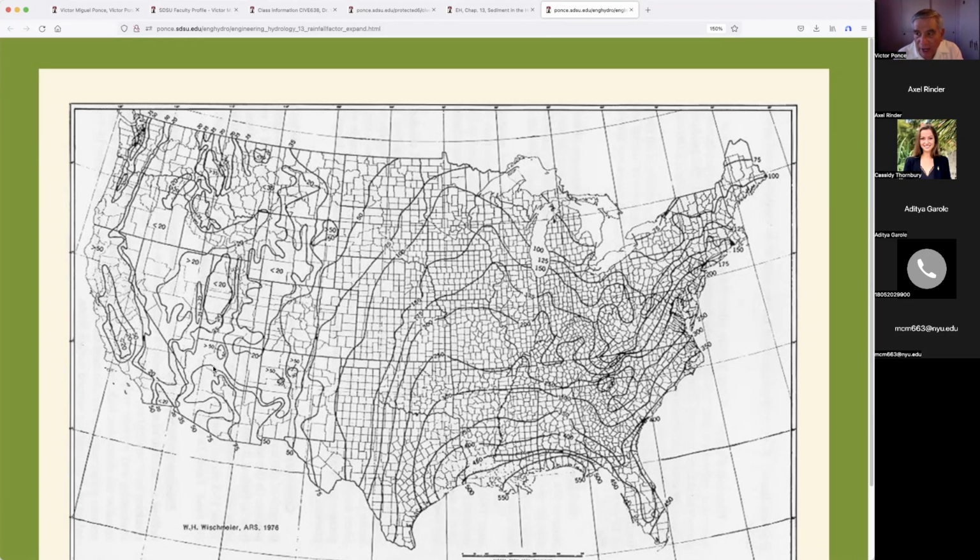And of course, in here we have EI. E is the energy, and I is the intensity. And we know that in California the rain is more intense. But that's a combination of EI. So E must be much less, so that it must be that it rains much less in terms of the full year. We're considering the full year over here because the report is going to be on an annual basis. So as you can see, these numbers for R in California are 20, 50, 75. And over here, in the Midwest, they get to be 200, 300. In Florida, 500.